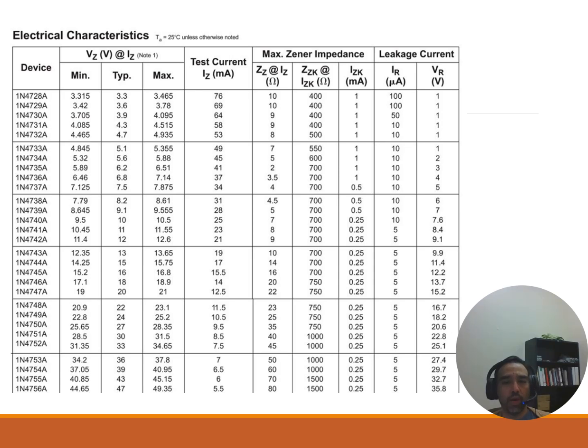So why is this important? We talked about ideally that a Zener diode shouldn't allow any current to go through, and we do that on paper, in the textbooks, the theoretical, and then we get into the practical, right? Practically, in reality, there is a tiny bit that goes through, and if that leakage current ends up being too high, it could affect the circuit when the diode isn't supposed to be doing anything. So a low leakage current just ensures that the diode doesn't interfere with the rest of the circuit when it's not in use. Right?